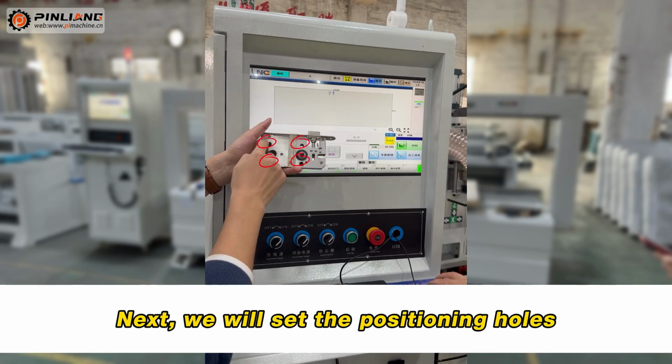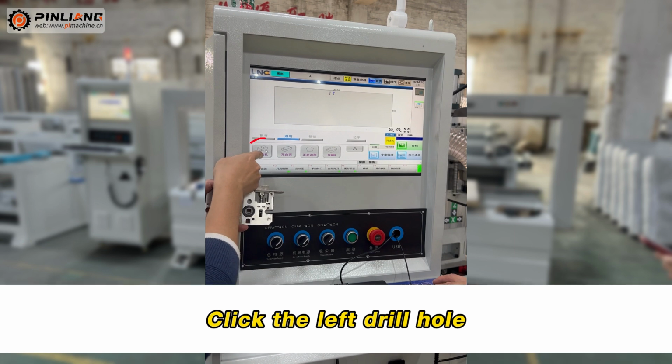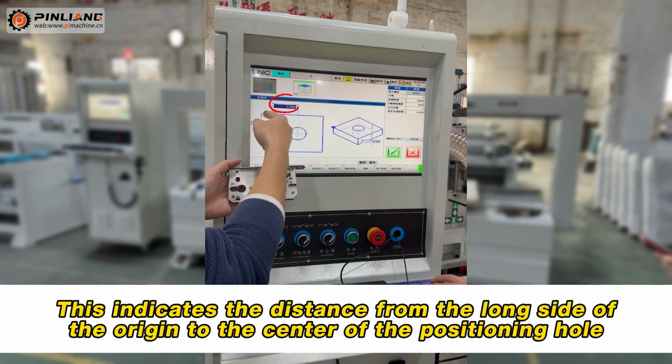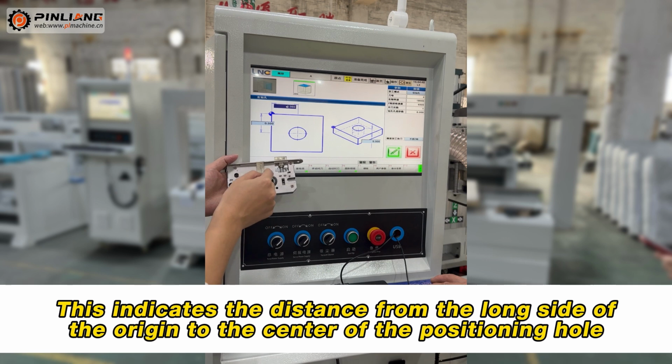Next, we will set the positioning holes. Click the next page. Click the left drill hole. Let's start with these 2 holes. This indicates the distance from the long side of the origin to the center of the positioning hole.